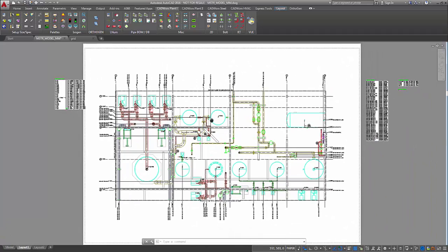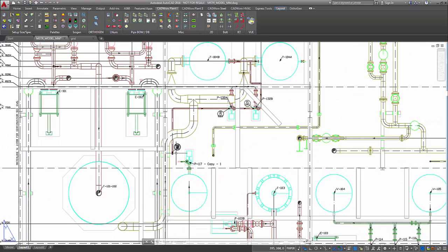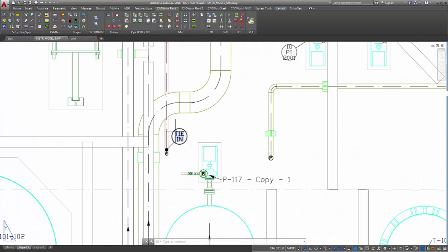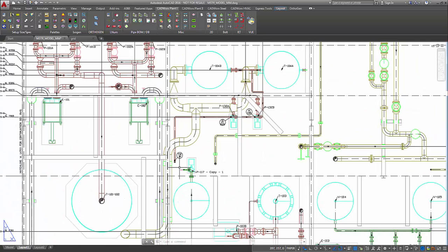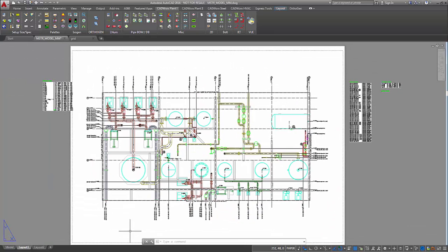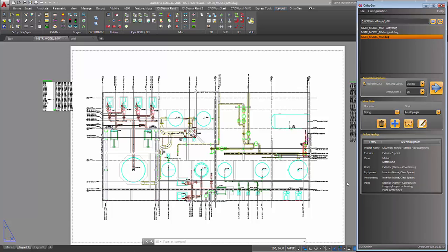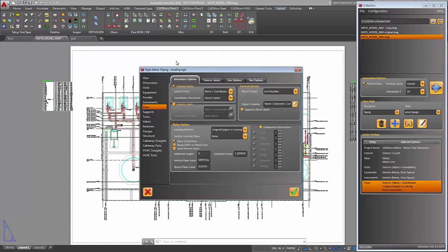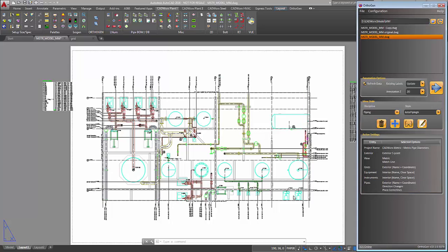Instruments, as any inline instruments, we also support the CADWorx OrthoGen supplementals, and we will annotate them as instruments. So using our other styles, for example on pipe, if it was a pipe rack, we'd probably switch to direction changes. Direction changes, as it implies, is going to generate more labels. It's a style we would use in the pipe racks.